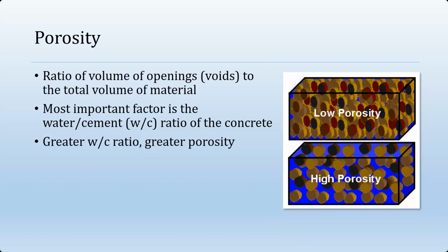Higher water to cement creates a more porous concrete and certainly a weaker concrete. The inverse of that, a lower water to cement ratio, typically will produce a lower porosity concrete, and certainly a stronger concrete. So when we refer to putting concrete down, we refer to it in ACI terms. We're placing concrete or casting concrete. So we tend to be concrete snobs in this industry.